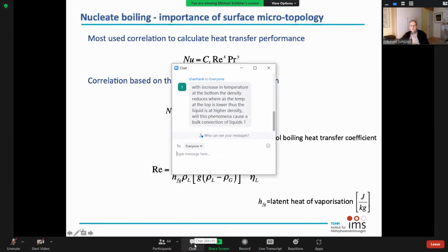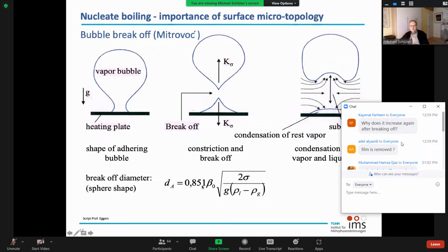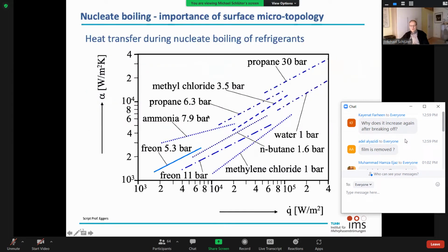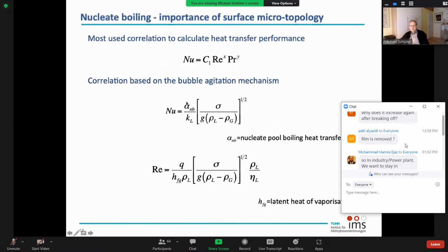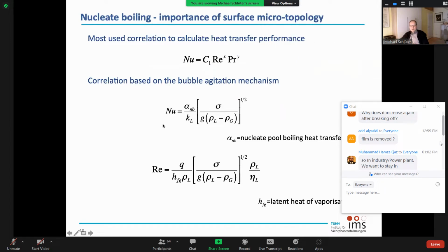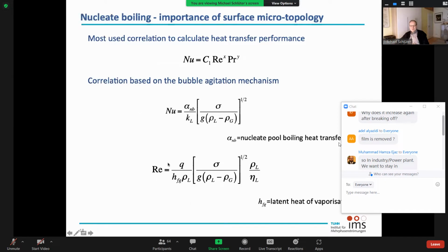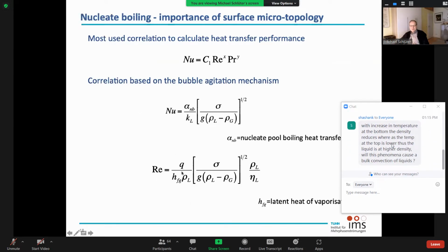And because we use adaptation factors with this alpha anyway, we can put these two correction factors also into our alpha, because we will estimate and measure this alpha anyway. So this is our equation for the pool boiling situation. And now we need another equation for the Reynolds number. And for the Reynolds number, we have defined the Reynolds number with this equation here.